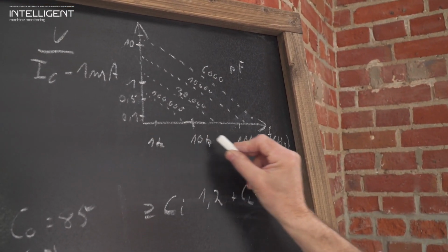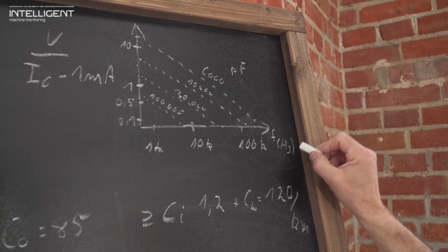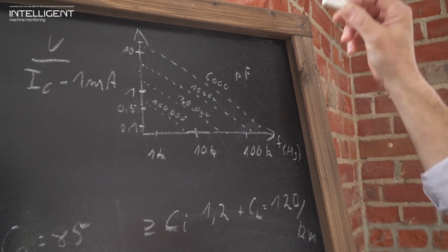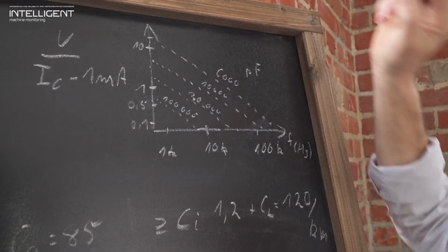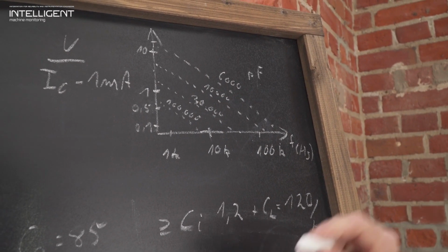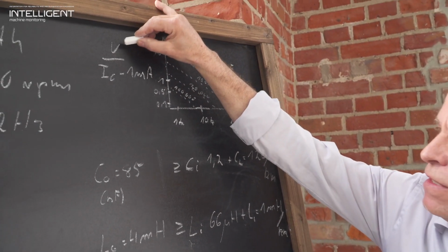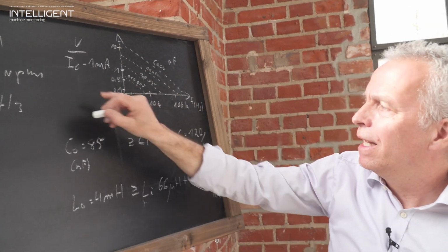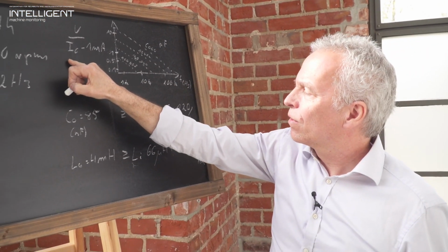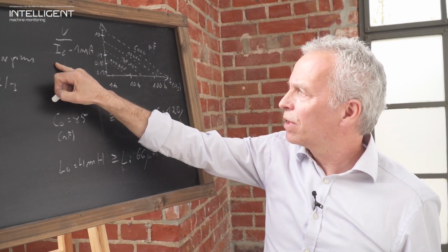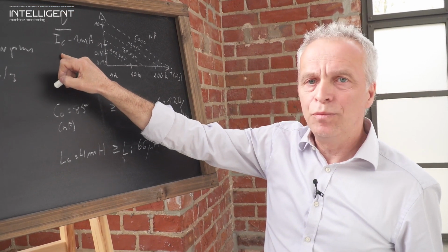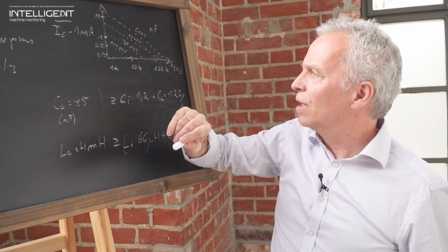So on the x-axis, we have the frequency in hertz. And on the y-axis, we have the relation between the maximum output of an acceleration sensor, in volt, and the constant current of the input card, IC, which is 10 milliampere, and we deduct 1 milliampere.